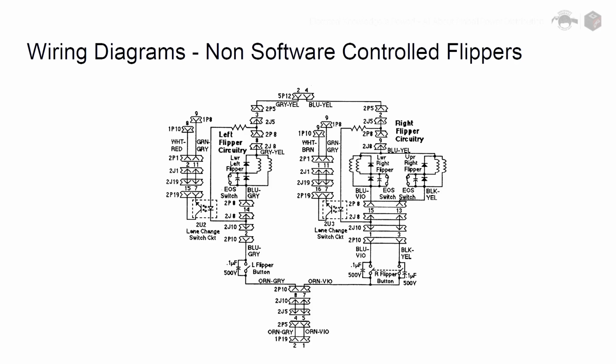So this is the flipper wiring diagram blown up. And what you'll see represented here is where the voltage comes out, the colors of the wires, what is connected through connectors and pins. This is the actual solenoid itself. There are 2 windings. That's what a winding looks like. These are diodes, and if you look on your flipper diodes, particularly parallel wound diodes, you'll see that there are 2 diodes, and they're often placed between terminals 1 and 2 and 2 and 3. And again, this is shown here.